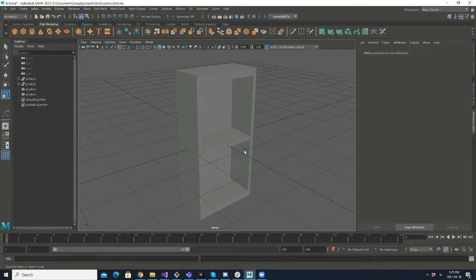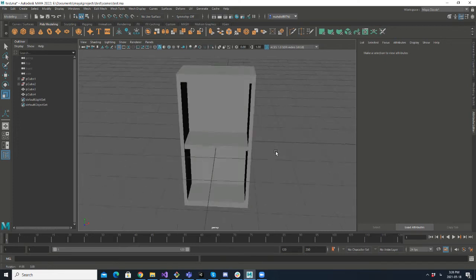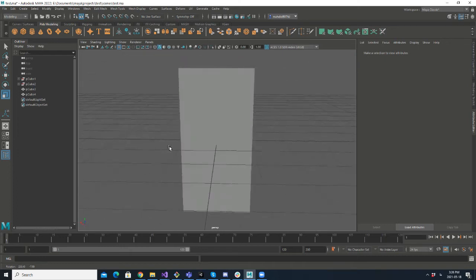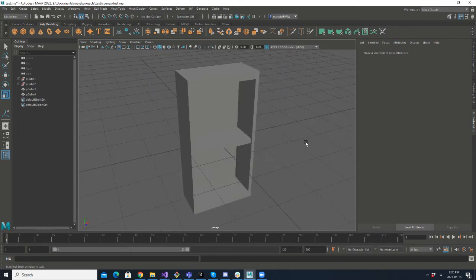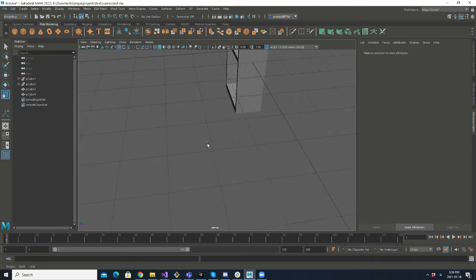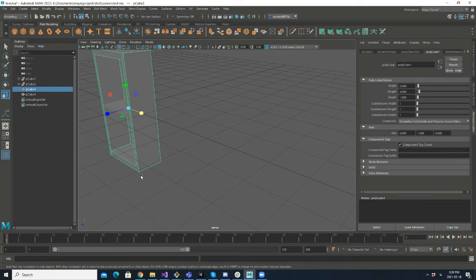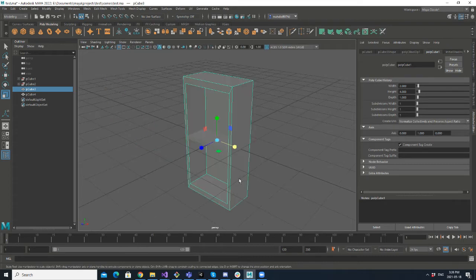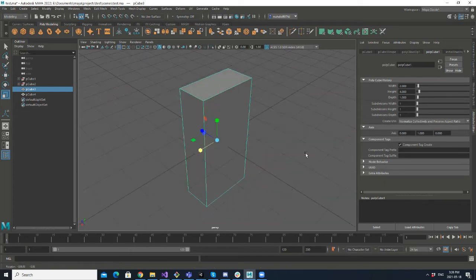And I think I forgot to say how you are going to navigate through the scene. So in Windows, by clicking on Alt and then clicking on the left mouse button, you can rotate in the scene around objects. And for example, if you go somewhere and you want to rotate around your closet instead of just rotating around nothing in the scene or around a bad object, you can just click on your object and click F. Then it's kind of focusing on the object that you want to take a look at, and now you can rotate around it.